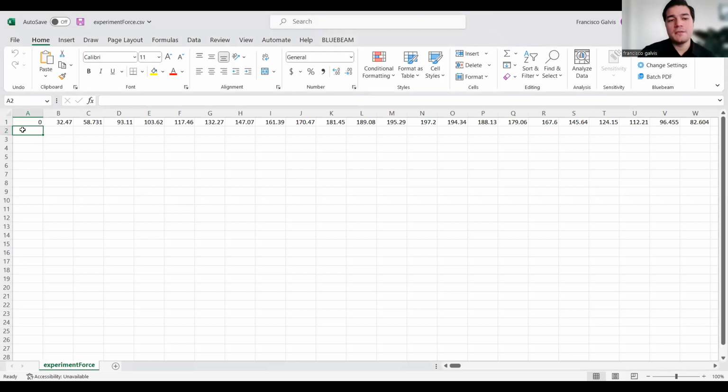Notice that we have arranged this file in a row instead of a column, right? And that's because that's how quoFEM expects outputs. quoFEM expects every output to be placed in a different column in the CSV file, which in this case means we have all of our results in a row. Why do we have so many? Because as we saw before, we have multiple increments in displacement.